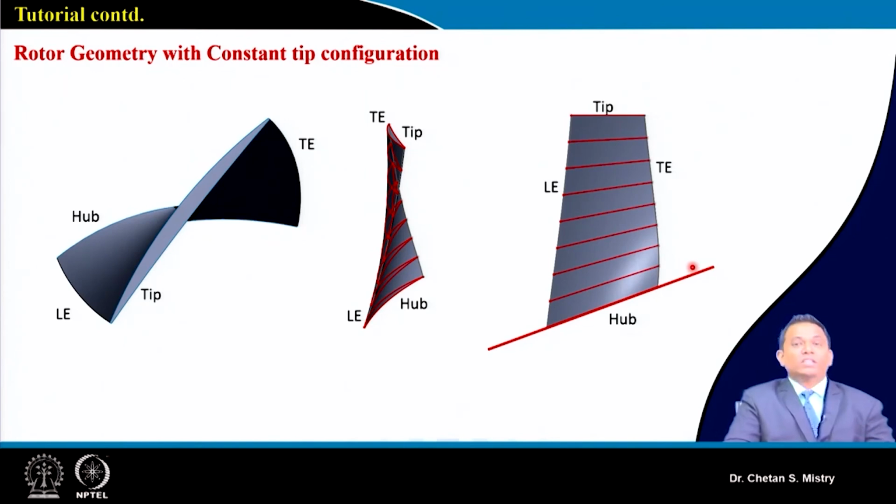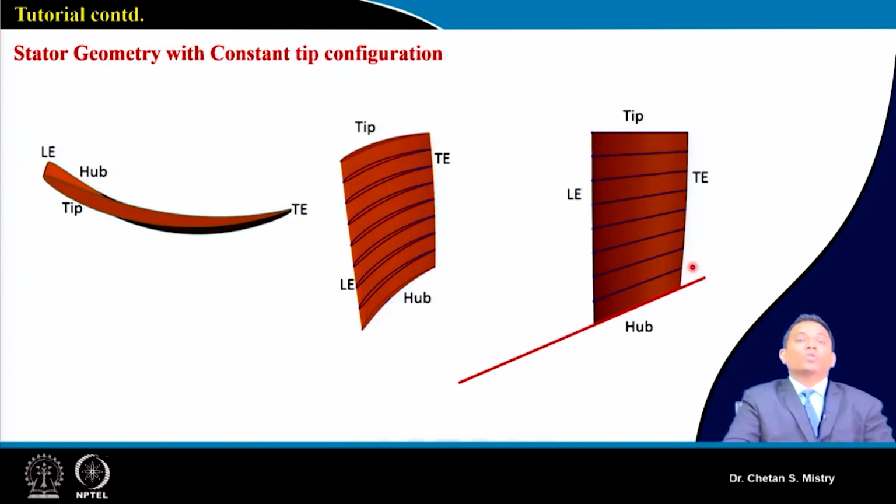Okay, now once this is done, you can have your stator geometry, and as we have discussed, our stator is a subsonic stator. So we will be using our C4 aerofoil. Here this is representing my curvature at hub and tip, and this is also stacked about CG. As per your requirement you can modify in a later case, maybe you can stack about the leading edge, maybe about the trailing edge. Okay, so this is my blade, and this is representing my placement of the blade.